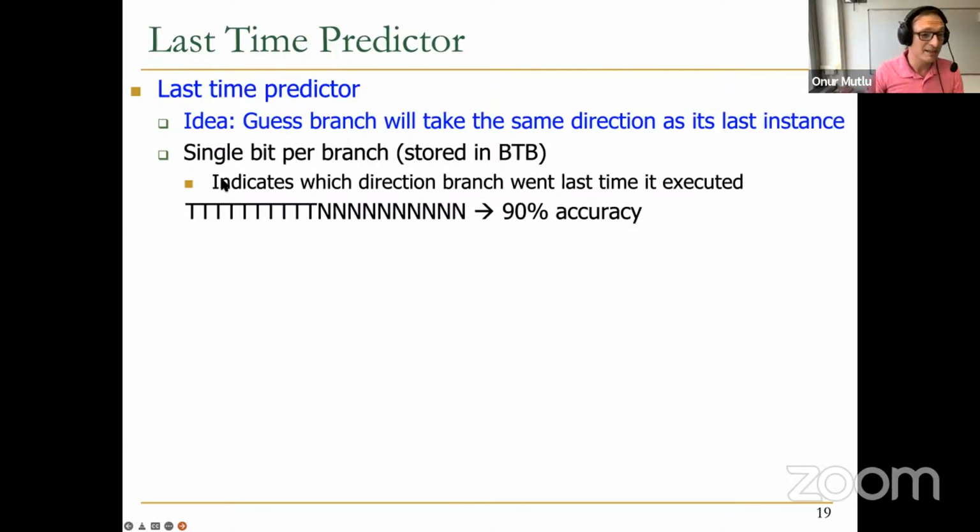And if this is the repeated behavior, in the steady state, the parts that you would mispredict are whenever the current execution doesn't have the same outcome as the previous execution. For example, here, we're focusing on this taken and not taken over here. In this instance, the previous instance was taken, so you predict this instance as taken, but unfortunately, the branch turns out to be not taken, so you flush the pipeline. So this is where you mispredict.